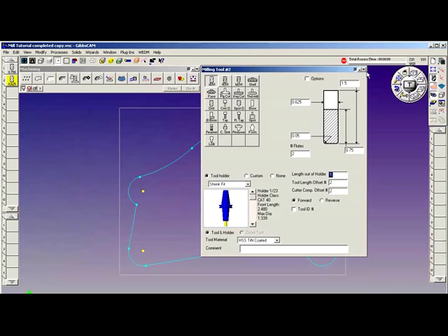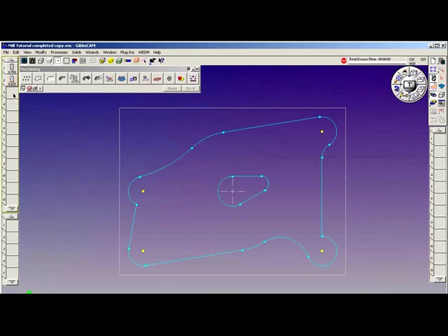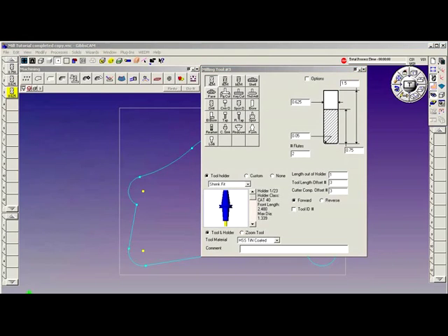Okay, close this, activate tool number 3. Tool number 3 is going to be a finish end mill. This finish end mill will be 1.5 inches long. The diameter will be 0.5, same radius, same length of cut, same length out of the holder. So pretty straightforward. The system remembered the previous settings, so all I had to do was change the diameter of the tool. Also, tin-coated high-speed steel.